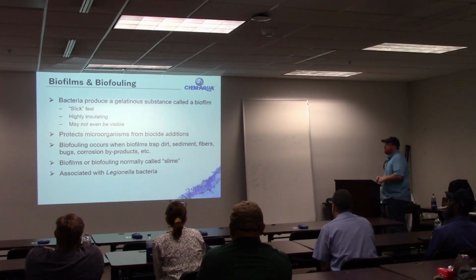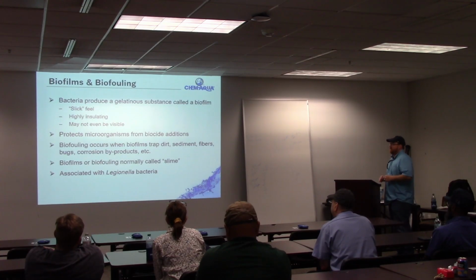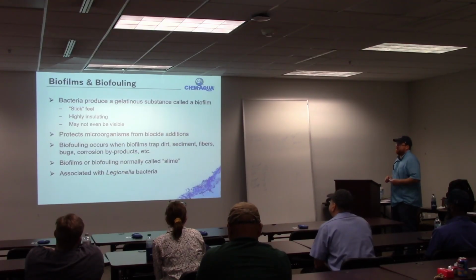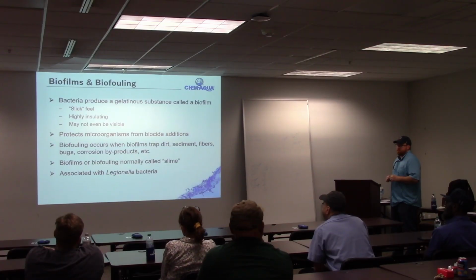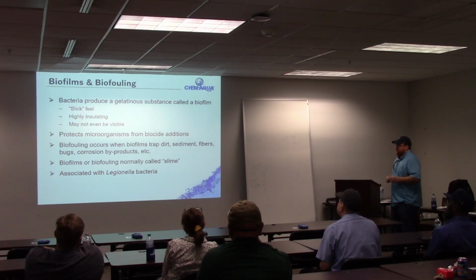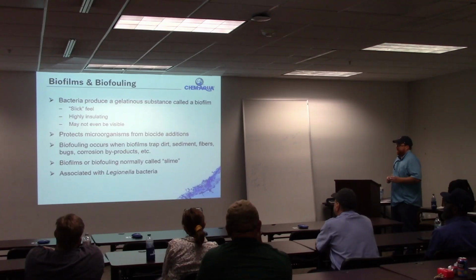All right, so we kind of talked about this earlier too, but bacteria produce a slick, slimy feel. They're highly insulating. Bacteria itself is not visible, but once you do start forming those bioslimes, it will be visible. And again, it just creates a lot of problems: corrosion, biofouling, insulation, bad heat transfer, and obviously, in some cases, Legionella. And Legionella does tend to proliferate when other bacteria are in higher numbers as well.